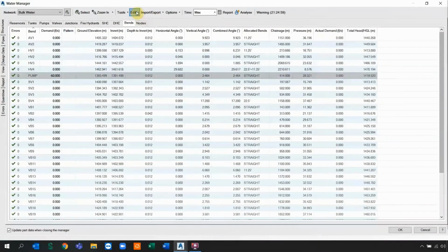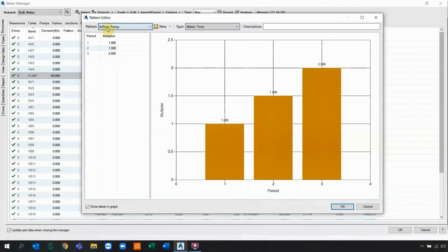And then I need to specify a pattern. The reason we specify patterns is so we can get more accurate results. Let's say, for example, I want half of this demand, say 0.5. And then I want an actual scenario. I want a pump that needs to give me values at 60 demand and then double it. So I have a nice little system curve.